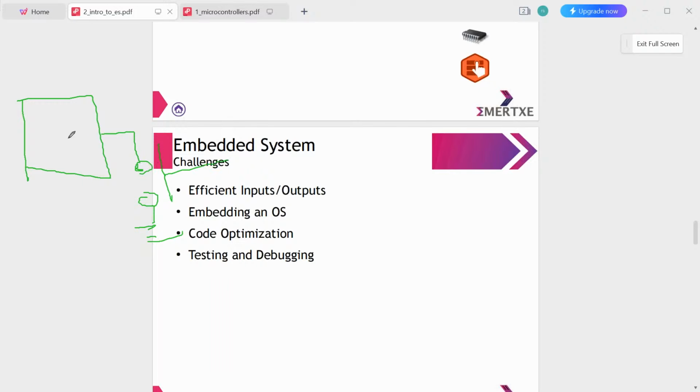You are saying literally 5 volt, but guys, in the previous case you said 0 because the connection was towards the ground. But here, are you able to see this pin? Is it connected anywhere? No. Don't you see this line is floating? Nowhere is it connected when the switch is open. Agree? Come on. Answer literally what you see. When you press the switch, the connection will be completed like this towards the ground. That's why you said 0. When the switch is open, this line is floating, nowhere it is connected.